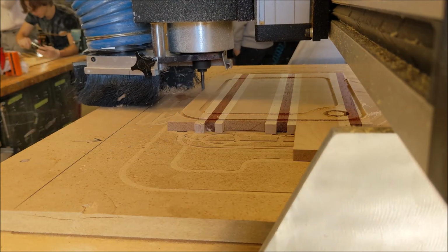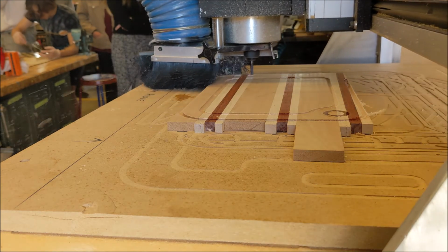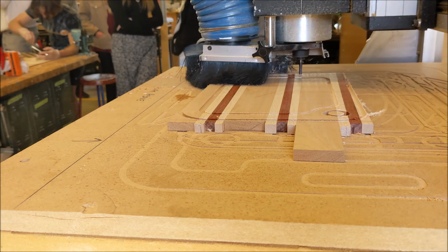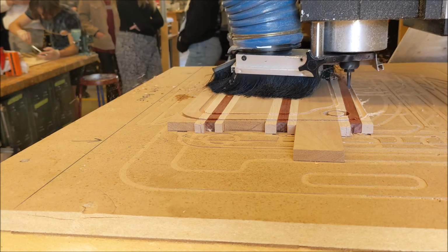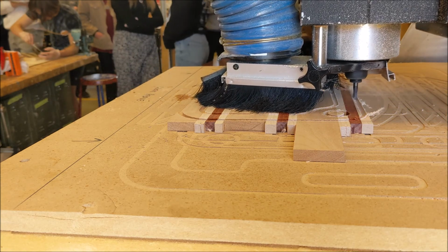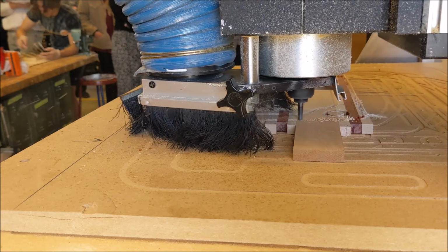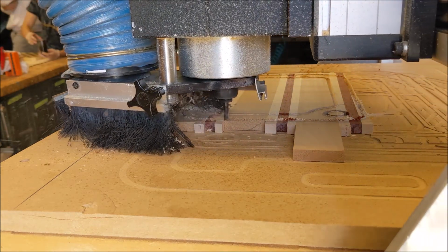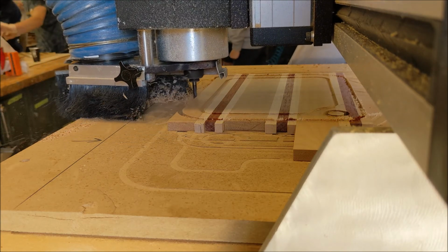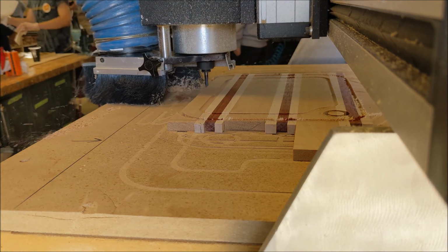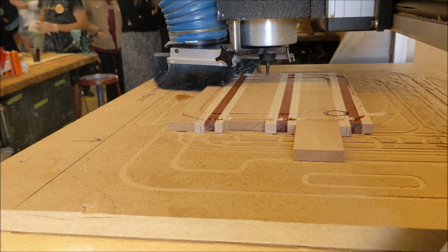On the hole in the center of the board, it was traveling counterclockwise and spinning clockwise, and that was a conventional cut. You can see right here it's going to plunge down at 50 inches per minute to do the second pass, and as it bumps up and down there, it's leaving little tabs in there, and that's going to help fixture the whole board down. This board is only a 1/2 inch thick, so the whole thing got cut out in 2 passes, and the depth of cut was a 1/4 inch.